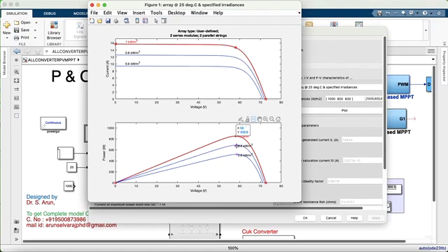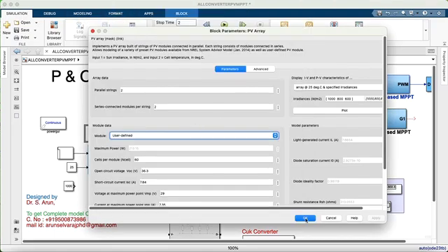The second curve is the 800 irradiance level. It nearly reaches 687.19 watts at the voltage of 58.38. The third one is the 600 irradiance level. It nearly reaches 518 watts. So this is the point to extract the maximum power at the voltage points. Okay, this one is the power curve, and this one is the current curve. It is my user defined function.